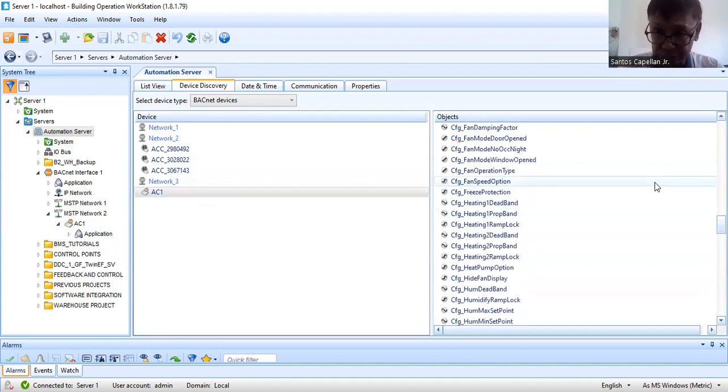Okay. Now, you should be consistent. Let's say you have around how many air coolers. You have to use the same control and monitoring points for each air cooler. So the next step is you need to create a simple graphics, then map or bind those points that you have selected to the graphics, then print out the graphics. It should be included in your material submittals for BMS.